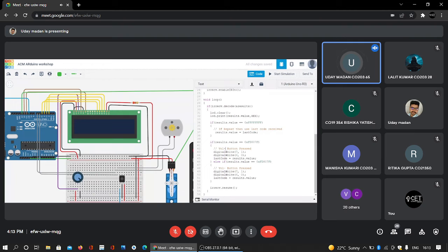So if the volume plus button is pressed, we were giving 7 positive and 6 negative in the top button. So we'll give the reverse here, so that our car moves in the reverse direction, and everything else remains the same. We will change this code with the volume minus button code, that is FD906F. Okay. So now our positive and negative are ready.